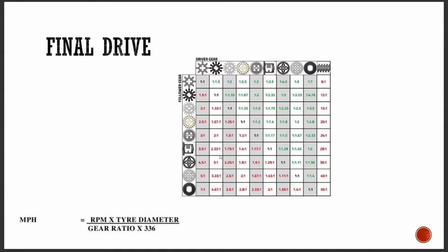So now we also need to figure out what our gear ratios are, because we will have a variety of gear ratios. Even though in our function I'm going to leave gear ratio as just a typical variable, we will have to find on that line that we graph where the gear ratios that we are working with are to determine what speeds we'll be running at. So from this visual up here, you can see that we're using this type of differential with this type of gear, and we can follow that to see it's 1 to 1.4.